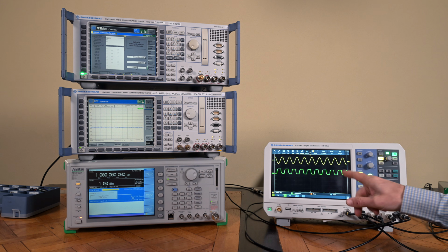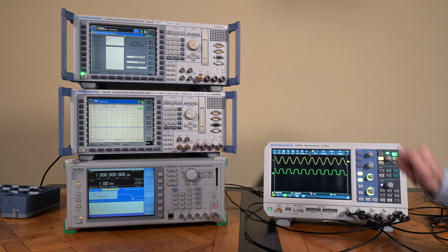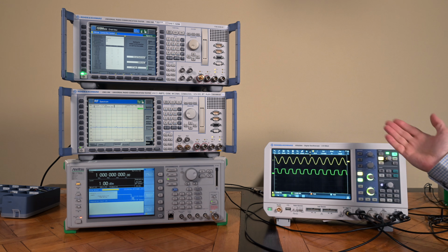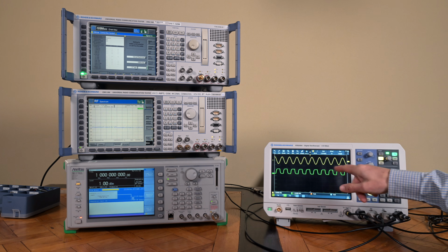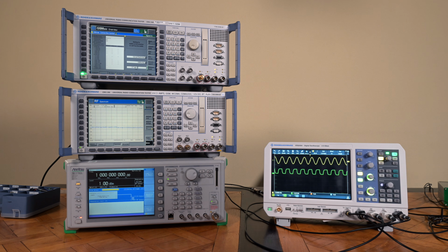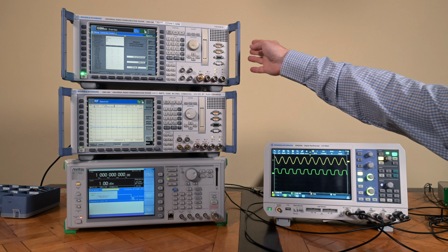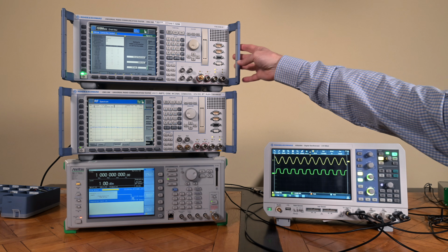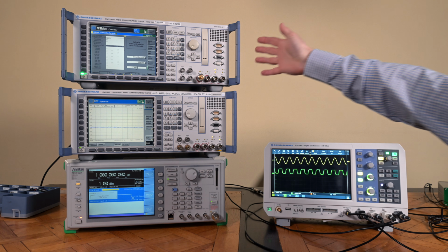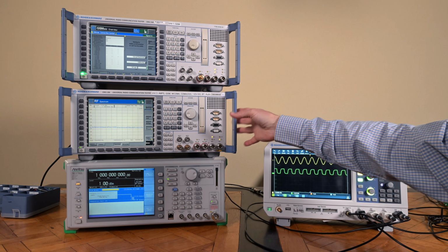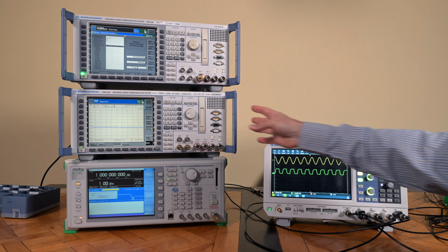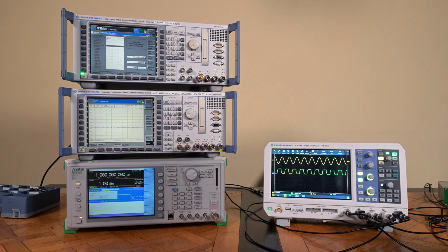And if we were at 1 megahertz, then moving every second would be 1 out of a million, so 1 ppm. But we're at 10 megahertz and then moving for 1 second, it's only a tenth of that, so 0.1 ppm. Let's see how the next one is doing, because this one has the B11 clock option. So that is better than the standard, but this one actually has the best one, the oven-ized option. So let's see if this one indeed is better.